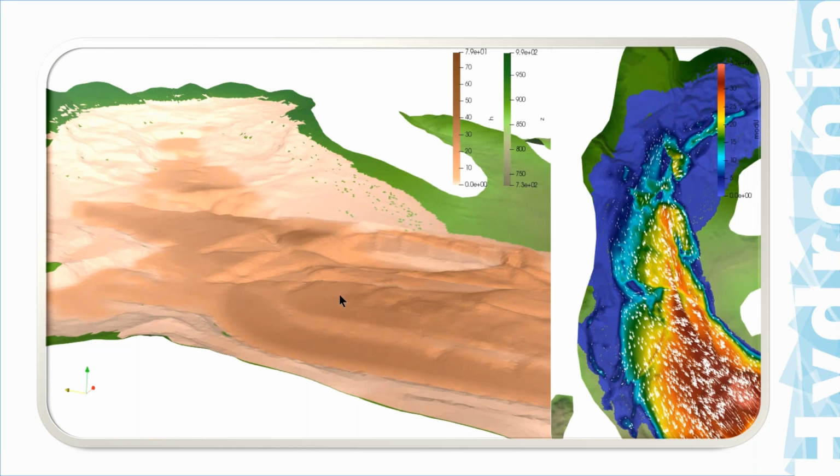Okay, I have a question in regards to the stress and the shear stress. I presented the yield stress that we used was 1200 pascals. We did a kind of calibration. We analyzed different values until we got the closest results. So we did a calibration in terms of varying the yield stress to represent the stoppage of the fluid, and also the viscosity to be in the ballpark range of the viscosity for this material.